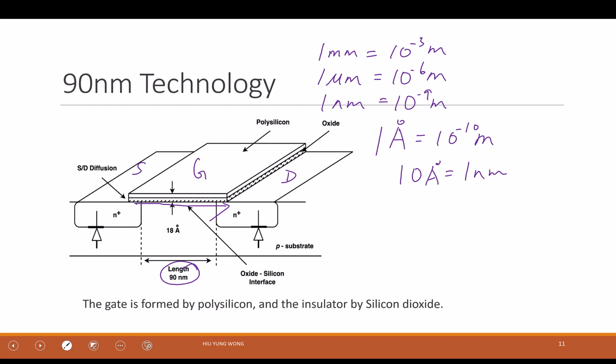It won't be leaky. But when we scale the transistor, we make it smaller and smaller, becoming 20 nanometer or 40 nanometer length, it will be too short, just like I only have 1 finger to pinch it off. So how can we increase the controllability?